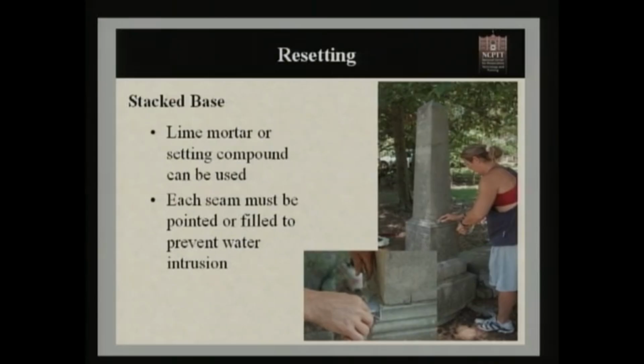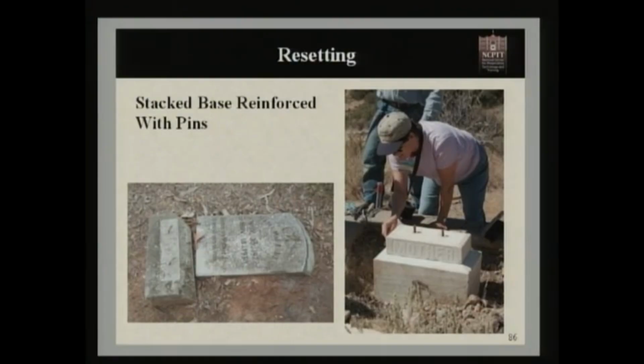And we want to make sure that the seam is completely filled to prevent any water intrusion, and that'll prevent any damage from that ice jacking that we talked about. If we have a stack base that has reinforcement, we talked about those metallic pins earlier, we're going to need to remove those. So let's talk briefly about those.